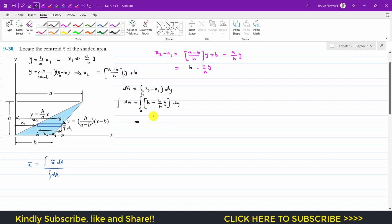Now if we integrate this, this will be by, and this is minus bh, and this will be y square divided by 2, and this is from 0 to h. Now if I put these limits, this is bh minus b divided by h, and this will become h square divided by 2, and if we put y equals 0, everything will become 0.